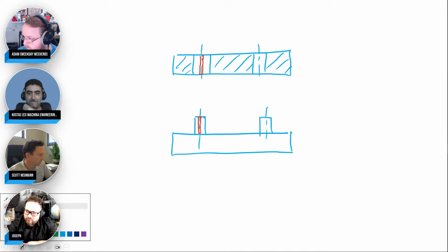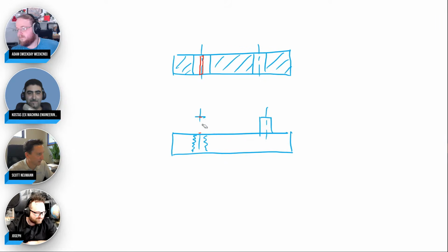The problem is when you go with a threaded hole, you're actually not tolerancing the thing that you care about. When I'm positioning, the hole doesn't mate with the hole. It's the bolt that goes into the hole. So you don't want the tolerance zone to be the length of the feature like it normally is. You want the tolerance zone to be projected out where the bolt is going to be.